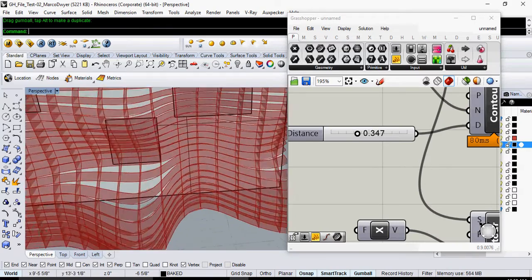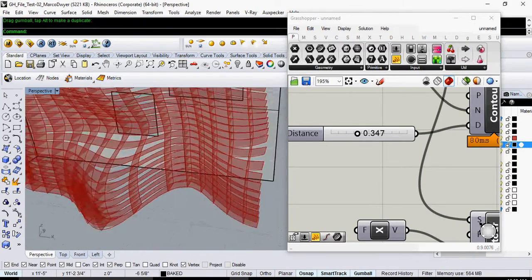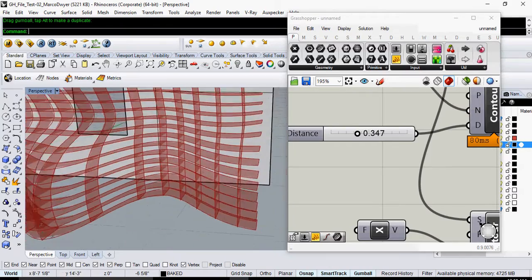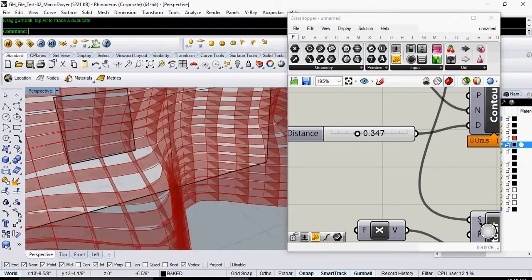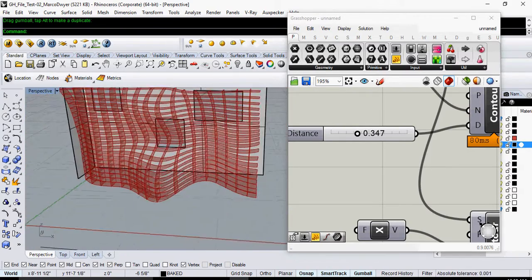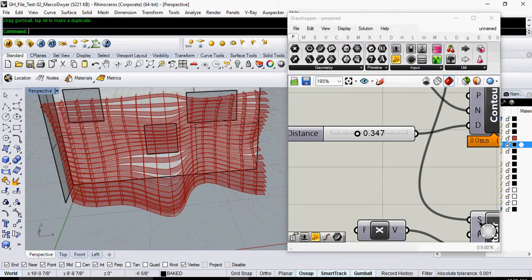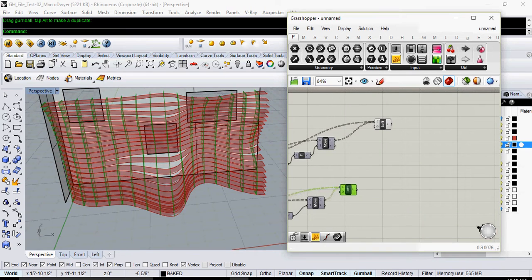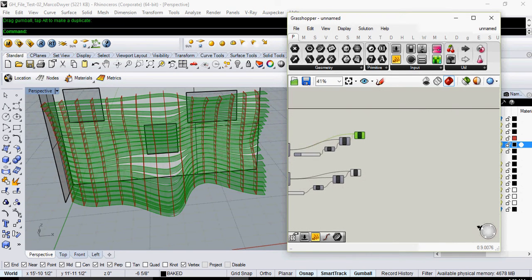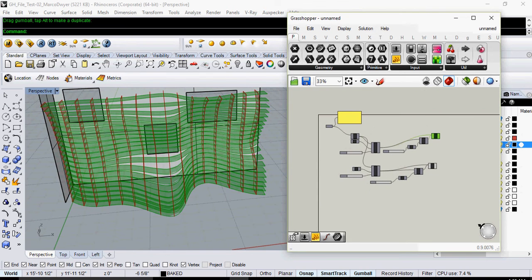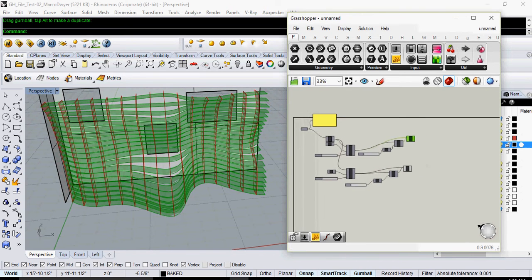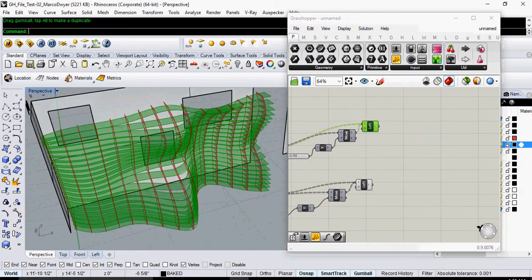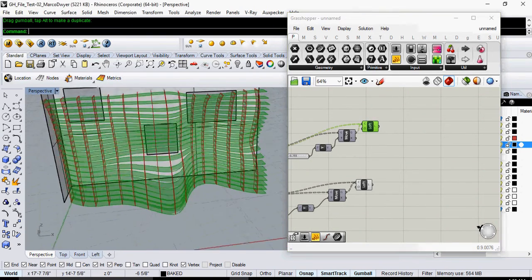So now these are all planar surfaces, you know. They have no thickness. We're not taking into consideration any thickness. So what I'm going to do now is go back here and start making this into a thicker surface, which is going to be the same concept. Nothing is really changing much from what we initially started with, just lofting and moving. So imagine I have this surface here. I'm going to select it, the green surface, which is loft.